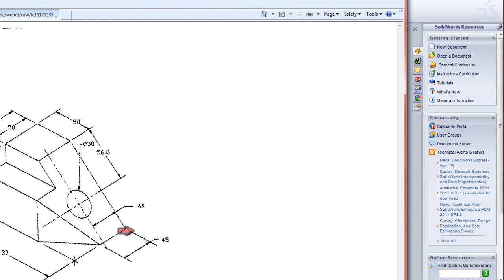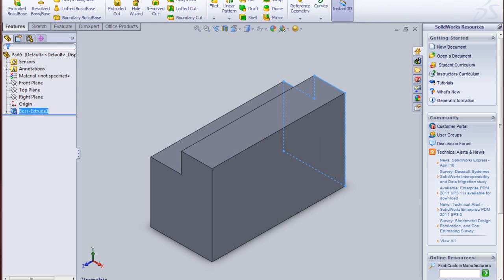I don't know what the angle is, but I know the location of this point and I know the location of that point. So in the sketch on that far side surface, I can create a line and then use that line to define my plane and create my own reference plane using this line and this point and this point. And mathematically you can create or define a plane using 3 points or a line and a point. So I'm going to go ahead and do that.